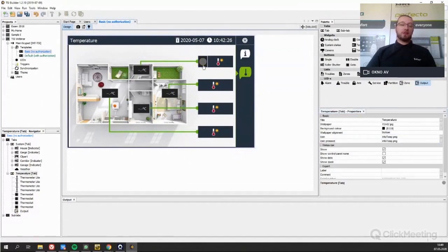So right now, what I have in here is information about the current temperature. I have the possibility to change the values of the threshold, whether it should already start heating or not yet. And then I have information about whether the valve is open, so whether it's sending heat to the room. I hope you understand the idea of what I did in here, but this will give me a lot of information. For example, I will be able, as the user, to check if I have set 21 degrees and right now I have 20 degrees.